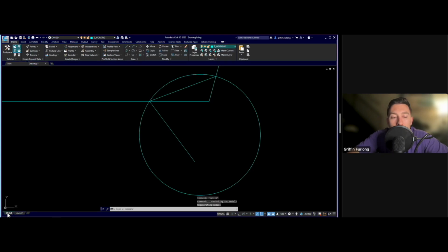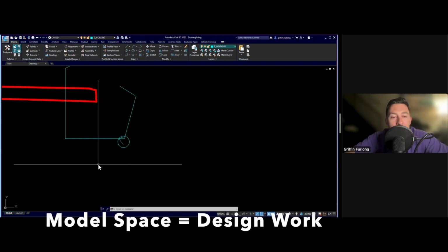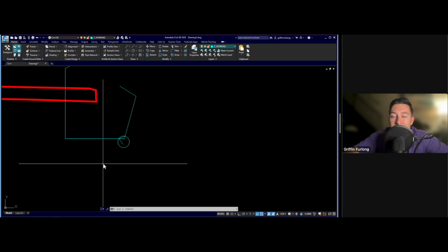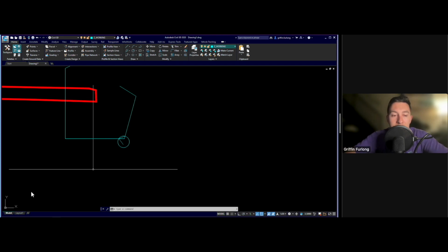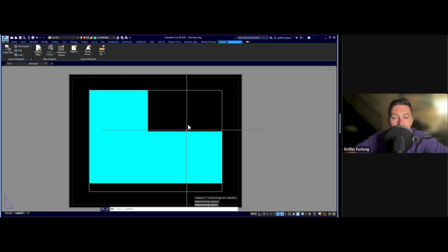So you have the model space tab, which is where we're doing all of our work. This is where we're putting in our external references, drafting lines, and basically building our model. Now, these other tabs are our layout tabs. Think of these as the sheets, the actual paper that we're going to print. This is the window into the design where we create viewports. And a viewport is like you are looking into a particular aspect of model space. And I'll show you what that means.